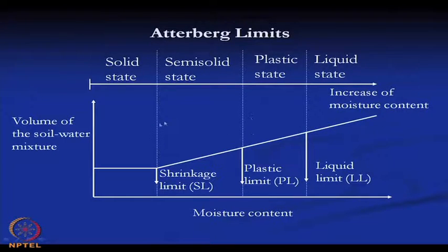Now, let me draw a graph of moisture content versus volume of the soil-water mixture. We can see that if we decrease the water content, the soil goes from the liquid state to the plastic state, then to the semi-solid state, and as we reduce the water content, the volume of the soil-water mixture also reduces.